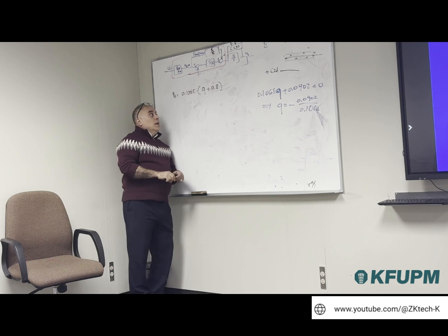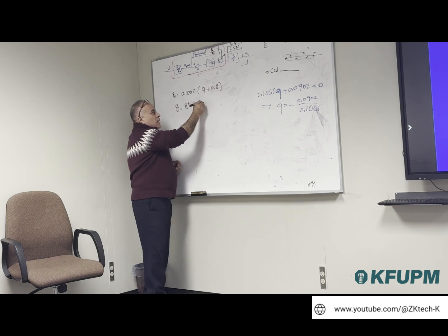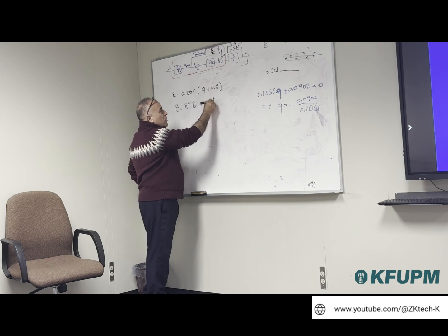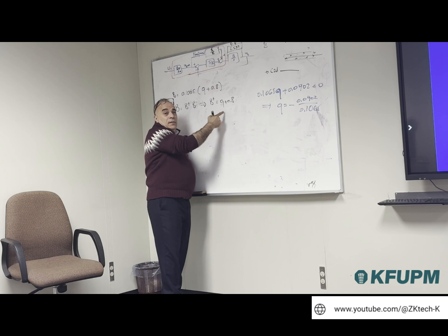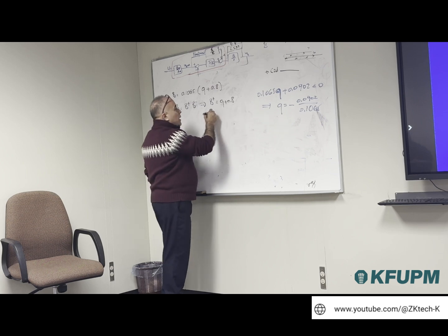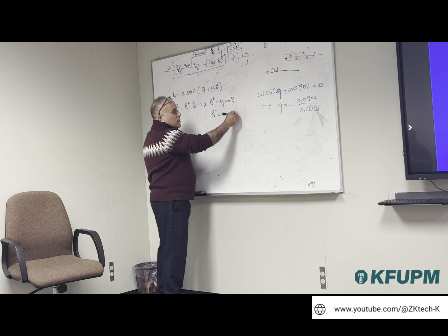Then when I decompose B into B plus times B minus, I can say that B plus would be equal to Q plus 0.8, a monic polynomial, because I accepted the zero and said it's okay. And then B minus would be equal to the constant 0.1065.